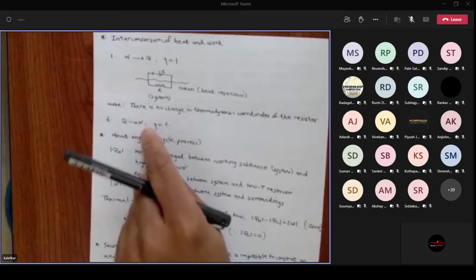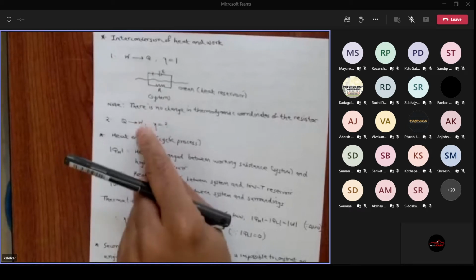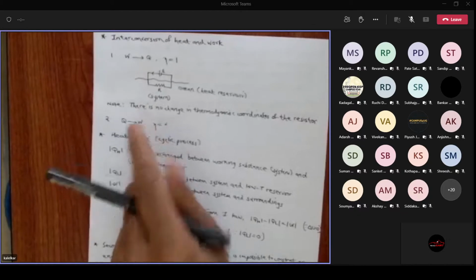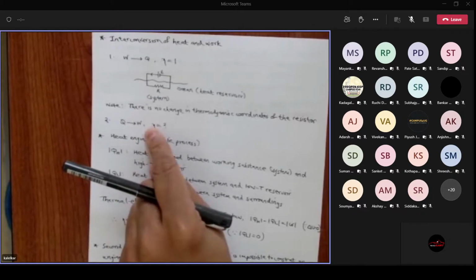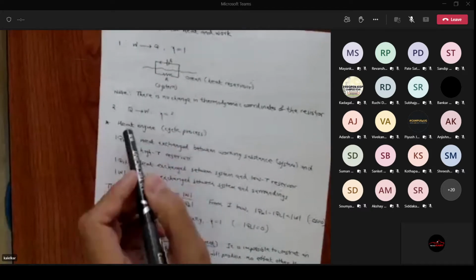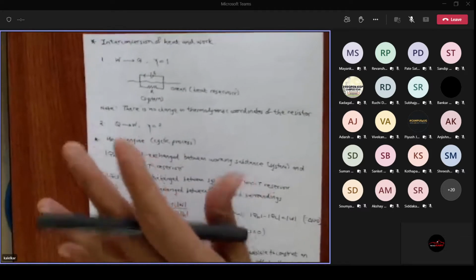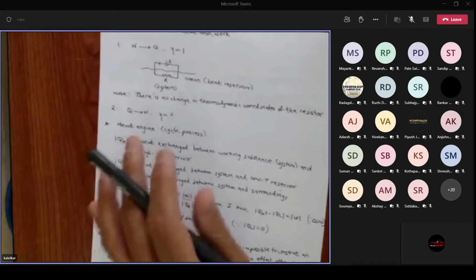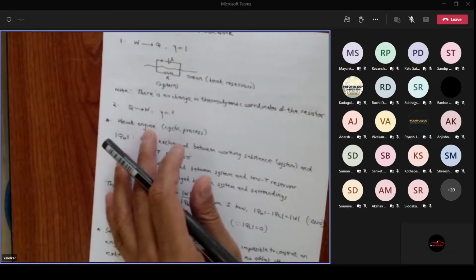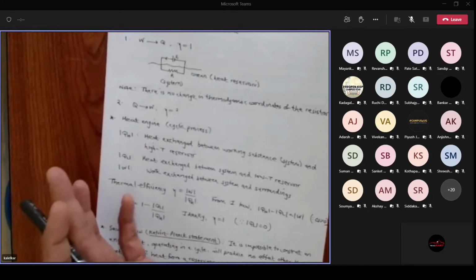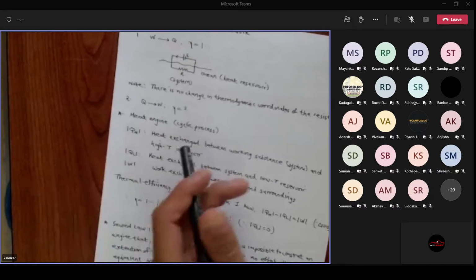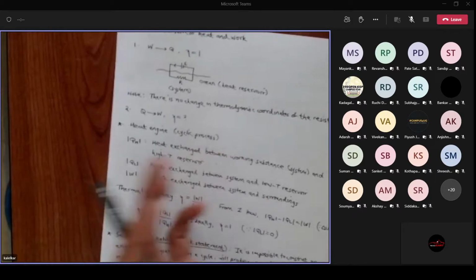That's because you have something called the second law of thermodynamics, which prohibits this from happening with 100% efficiency. Thermal efficiency. So to introduce the second law, this is actually how it was done historically. Because in the 19th century, during the Industrial Revolution, the main focus of engineers and, in a way, scientists was to make more efficient heat engines. That was the main driving goal.